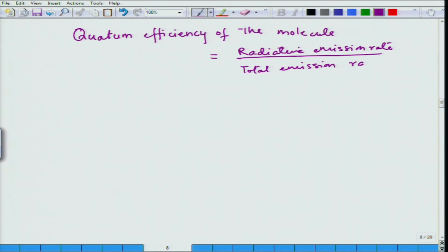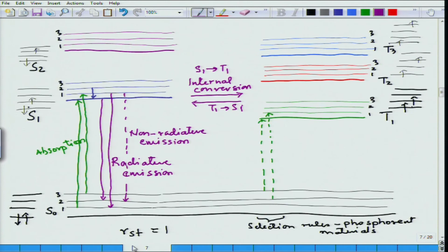And this is very similar to the discussion in recombination generation of inorganic semiconductor. This quantum efficiency is given by 1 over the radiative emission decay constant for the molecule and 1 over the non-radiative decay constant for the molecule. So, if we have an excited state which is responsible for the emission in the OLED, we are going to have a higher quantum efficiency for molecules for which this is small, that is a loss in the OLED part.